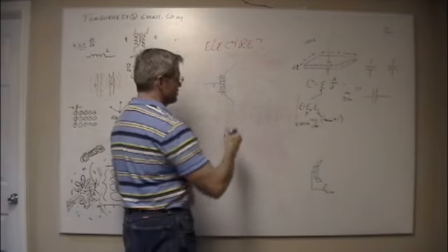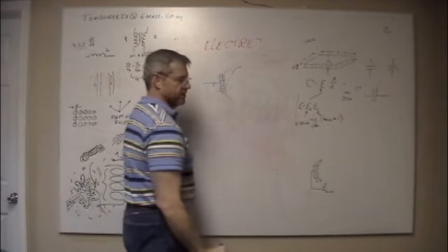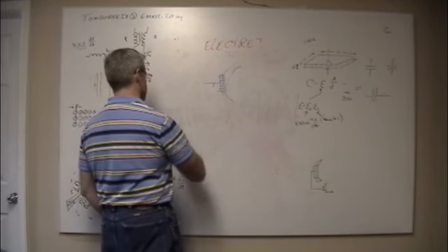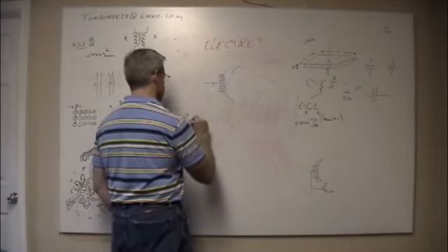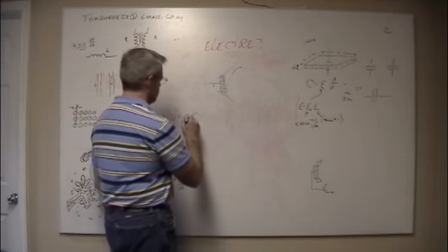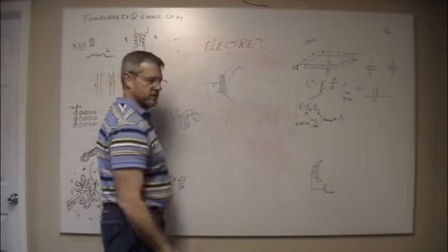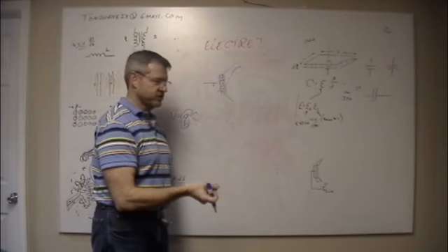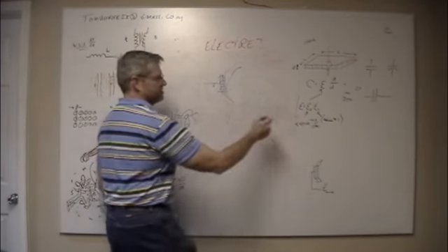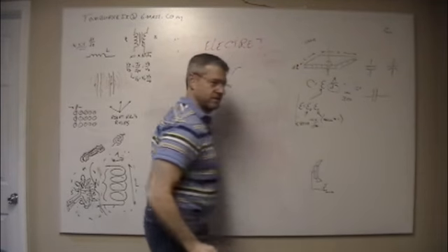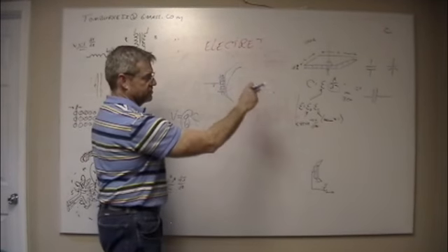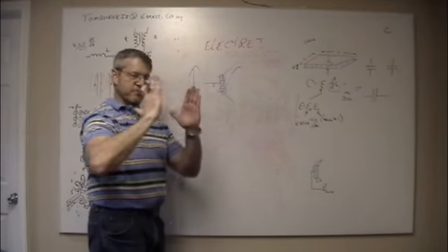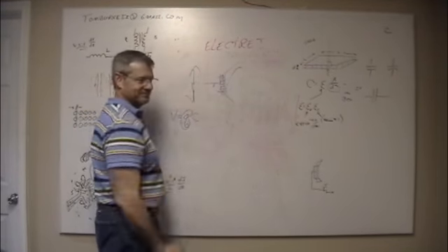Now when I talk and a sound wave hits this, it squishes it closer together. V equals Q over C. Q is constant because those electrons are loaded in there as graphite particles or whatever else, so it's not going to change. But my plate dimension changed. Plates got closer together, capacitance went down, that means voltage went up. And now as they move apart, voltage goes back down.